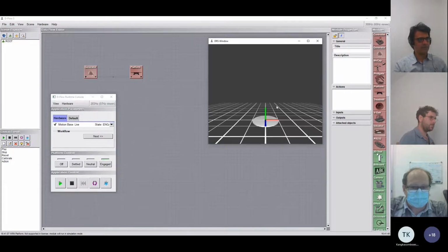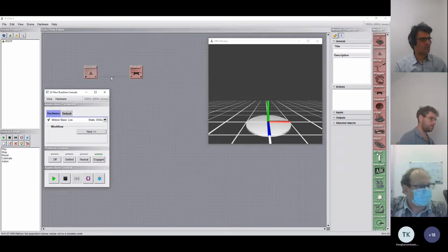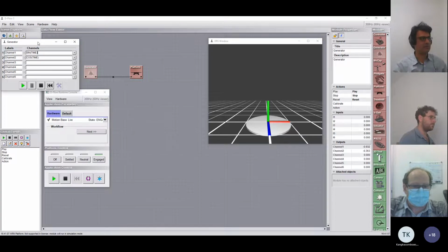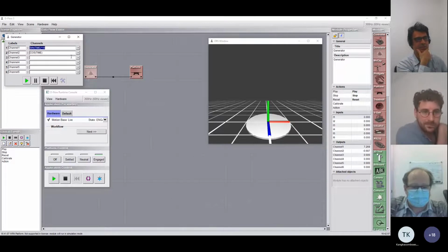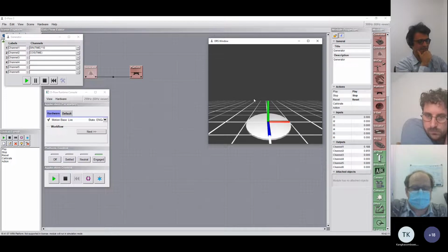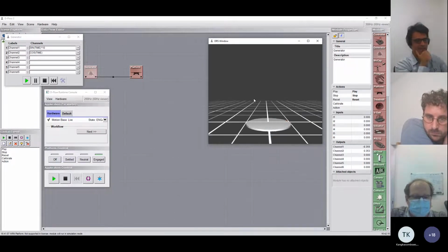So that is moving. It is still quite small because it's a sine of 1, and rotation is in radians, so it's not much. Maybe you can say times 10 so that the changes will be obvious. You can also remove all these things: click there and press G, and that will be gone. If you press A, the axis will be gone.